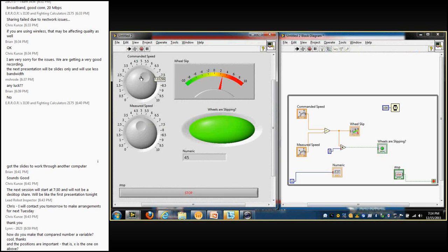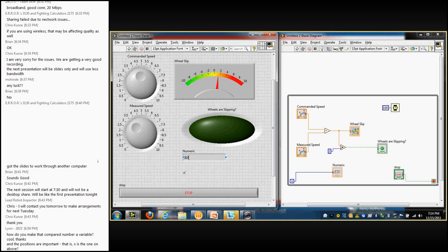There's no lag at all in the way that the screen updates. But instead of running 43 million times, it ran 84 times. And so that's freed up 43 million calculations to do something else in your robot. Something that you definitely want to pay attention to: you want to time your loops inside of your programs. Most things that come with the default project will have things like this already built in or will use timed loops, but this is something to watch out for.